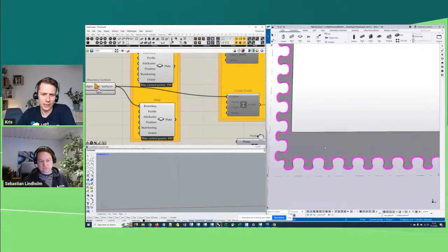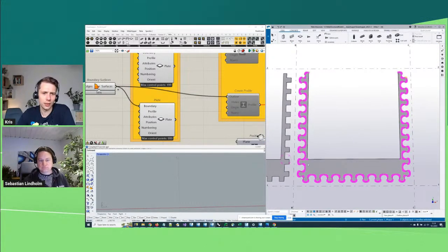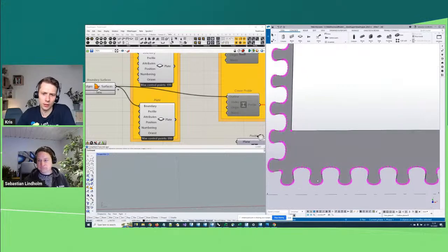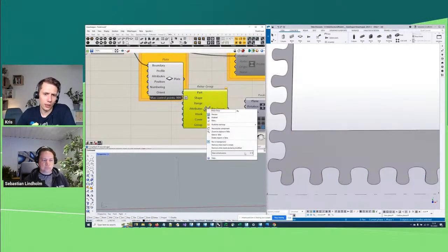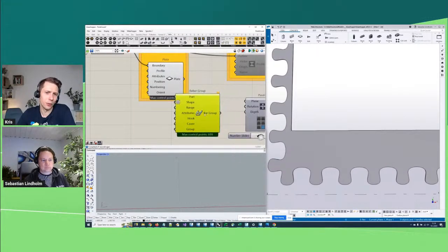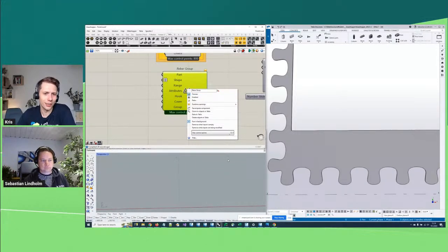It's the same with the reinforcement. Just a tip for everyone, you can also control the number of points for the reinforcement. For example, if you have some reinforcement in a curve, you can play with that and save a lot of memory, because usually there are thousands of reinforcement bars, and if you use, let's say, 100 points for every single one, it can cause problems, but you can change it really quite quickly. That's a good tip actually.